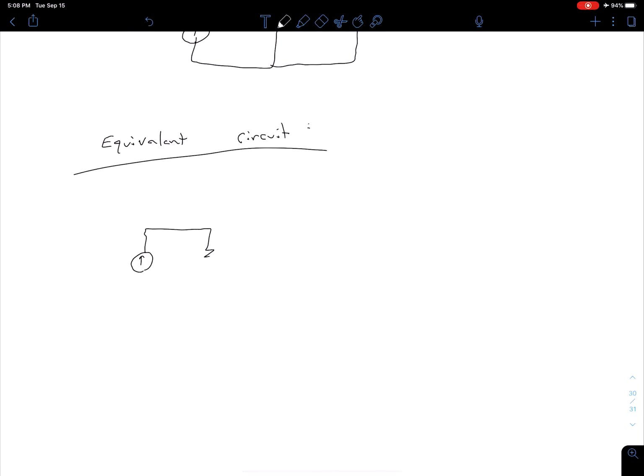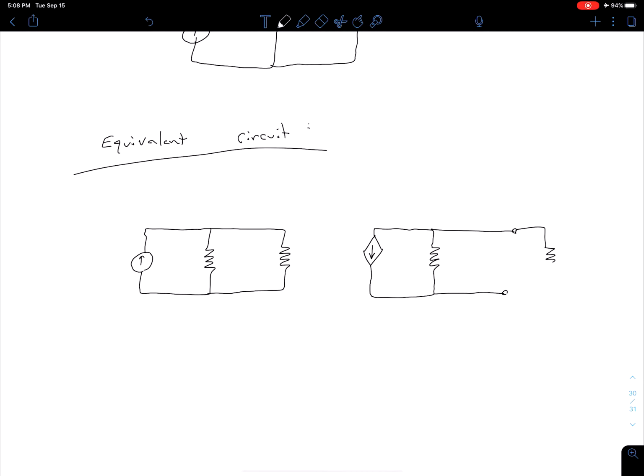So we have our input current, our source resistance, and then we have our equivalent input resistance to our amplifier with feedback. So we have our amplifier amplifying this by some closed loop gain. We're going to have our equivalent output resistance, which we just found previously in this video. And then we have some load connected to our amplifier. So let me come back through and label everything now.